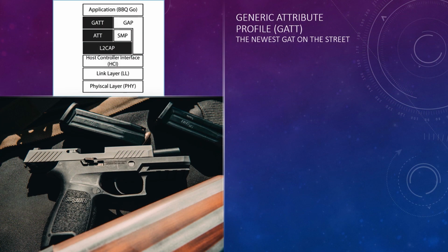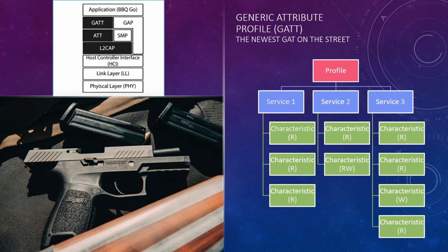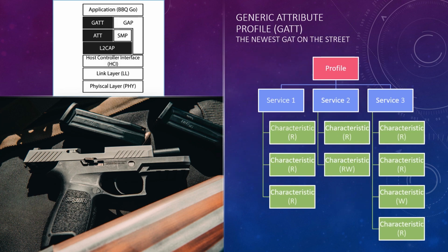Once we get connected to the device, we'll then begin to interface with what's known as the GATT. Not that kind of GATT, this kind of a GATT. This GATT is essentially a nested structure that allows for different data points to be accessed from the device. The way that it's normally laid out is the GATT server is what's going to be running on the device that we're connecting to. So in this case, our barbecue thermometer is going to be running the GATT server, and the GATT client will be initiated from our end with our program when we connect to the device.